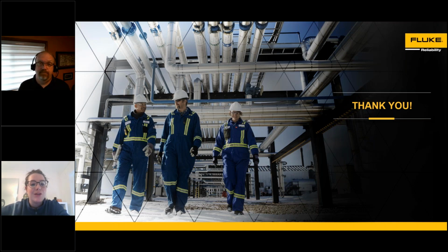Awesome. How do you weed out false alarms? Well, when you're using remote condition monitoring, that's where the nuance comes in. So you have false alarms where you have machines running right next to each other, and you're having some transient vibration and things like that. So you have to weed out false alarms by going and doing the legwork. You go and you learn what these frequencies are, and you may find that things that seem like a false alarm are transient faults, instead of transient vibration. So it's something that's happening in that machine, but it's not happening at all times during its production process. So keep an eye on it, and eventually you'll figure out which ones are real and which ones aren't. That's why vibration analysis is nuanced. Cool.